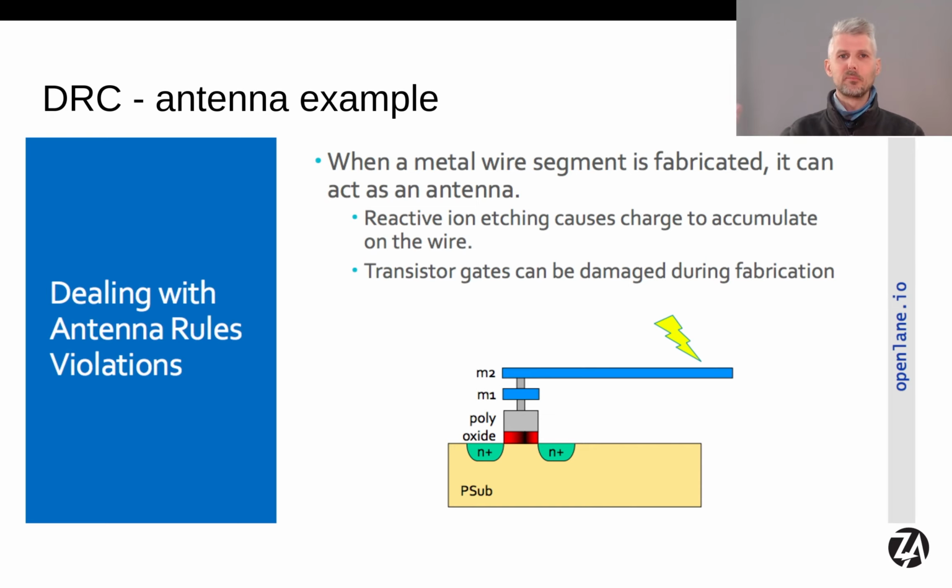And then in the flattening and polishing processes of building up these subsequent layers on the wafer, we can end up charging up one of the connection lines too much that then electrostatically destroys the gate, and we destroy the chip in the process of trying to make it. So we obviously want to stop that, so we can have a rule that basically checks the length of these antennas, and if they're too long, raise an error.